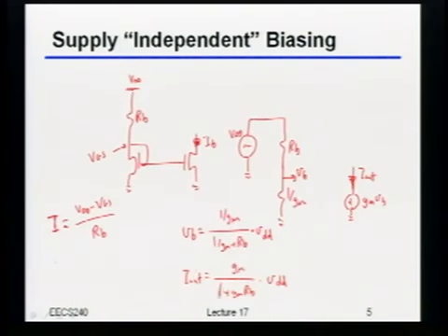Here, I can kind of make this work, but really the only way I make it work is to make GM really big relative to RB. Excuse me, relative to 1 over RB, of course. Which I can kind of do, but there's only so much room that I have to play with, right? So instead, what I'd really, really like is somehow to get rid of that VDD, or make VGS directly track with that VDD, okay?